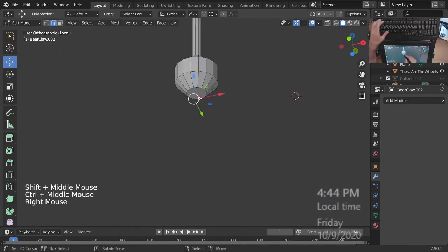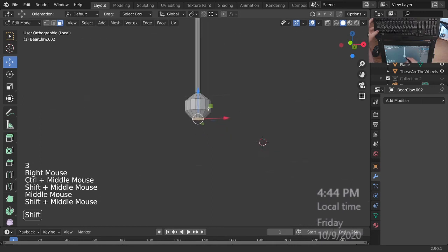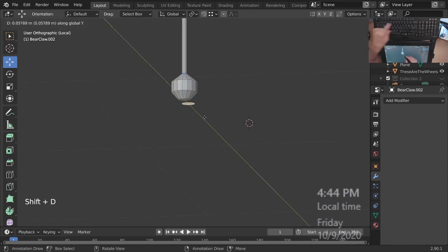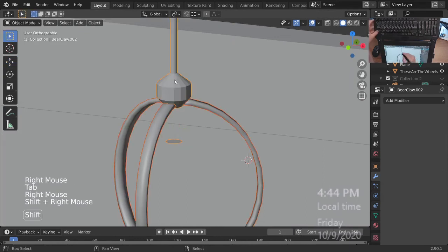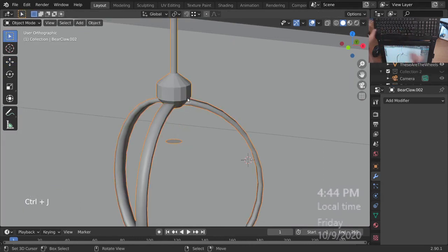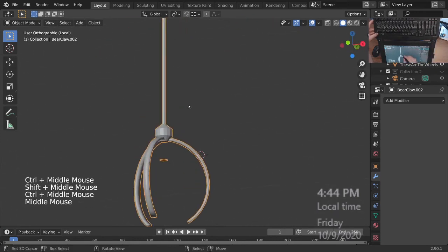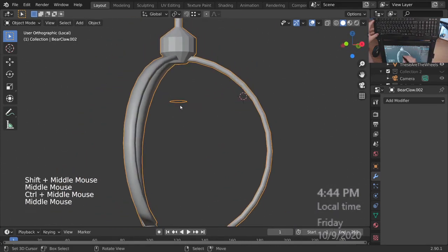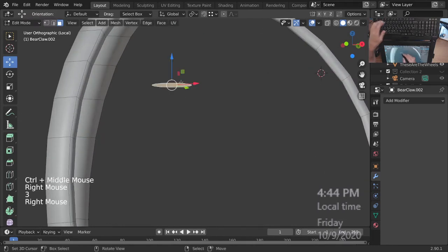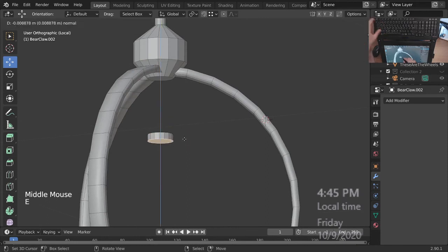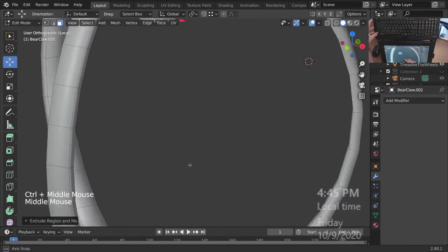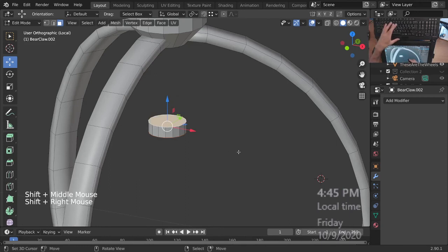All right, now taking that one, let's go into the local view, take this face, duplicate in the Y and the Z rather, and it's going to be around right there. I should have brought in this as well. Tab out, join them, why not? Control join, go back, tab in here, select that face, extrude it a little bit, inset it a little bit.